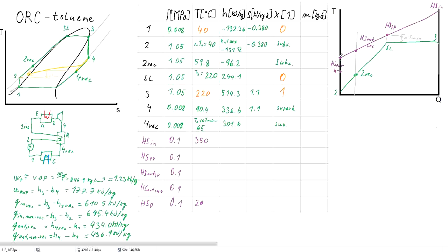It would have justification, for example, in some case of closed loop heat source, for example, some solar application, or more or less also in case of some biomass boiler, where we would have closed cycle and where what counts is the absolute value of heat input in kilowatts and not the given heat source with temperature and mass flow rate.